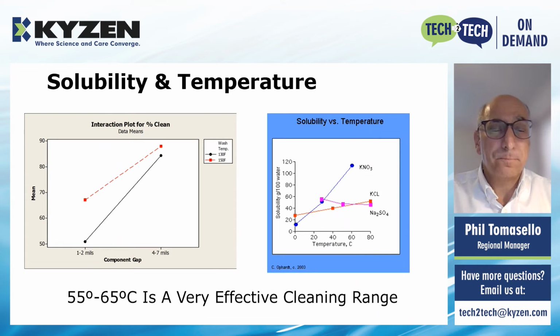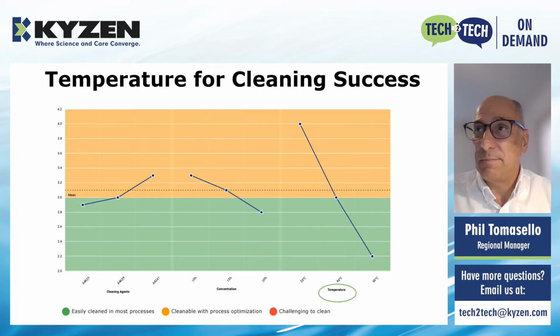Another few charts here to illustrate my point, solubility and temperature. Typically, the higher the temp, the greater the solubility you're going to have. Again, here, if you look perhaps on the far right-hand side of this graph, just looking at the temperature, easily cleaned. In most processes, you'll find 60°C. The lower you go with Celsius or Fahrenheit, candidly, the lower the temperature, the more challenging you're going to have of a time cleaning without really optimizing that process.